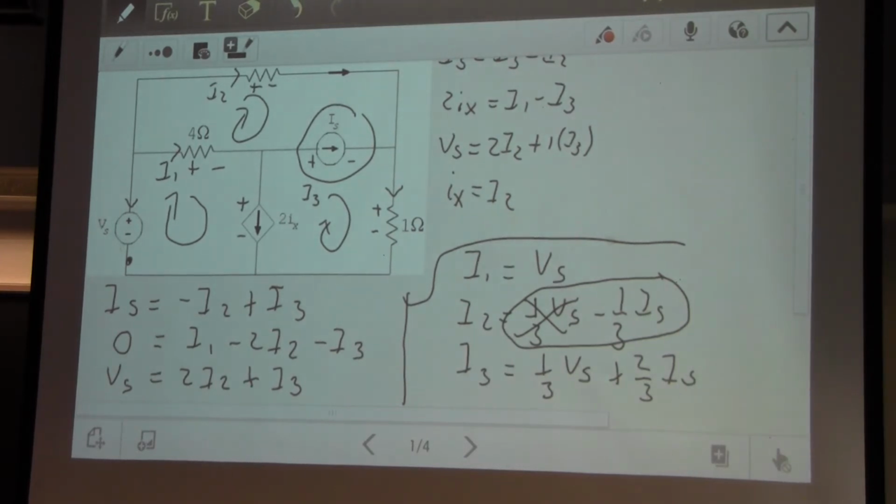This is going to be more clear now that I explain it, and then we're going to do an example there. But basically what you can do now is look at each source separately, get rid of all the sources in the circuit except for that one, solve for it, and then do that for the next source, solve for it, and then do that over and over again until you cover all the sources and then add all the solutions. And then it's the same thing.